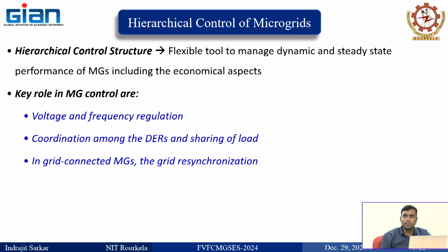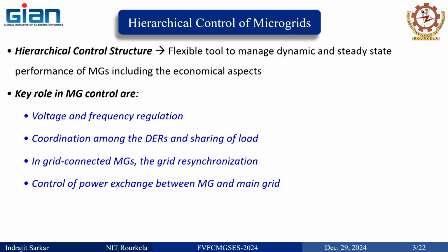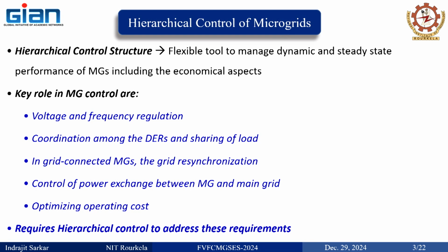So see, resynchronization will be there, that it will take care. As I told you, there will be a control of power exchange. There is an active and reactive power exchange with the grid. Active power is necessary, and reactive power is for voltage control. From voltage control, the reactive power will come. Operating cost. So we need a control, not necessarily a hierarchical control, but it is found that this is one